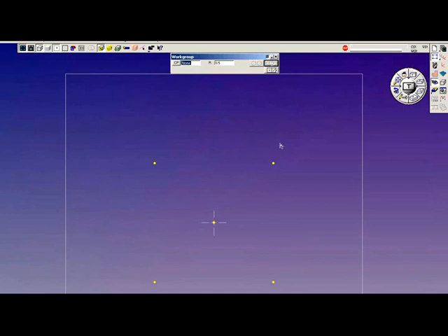If I need to draw a circle without a point at the center location, I can click on the CP tile, get the pull down portion of the menu, and do a point at X. I'm sorry, a circle at X2, Y0, Z0, and generate a circle there. And then we will just make a line from here to here, just to have a couple of features to illustrate the midpoint function.